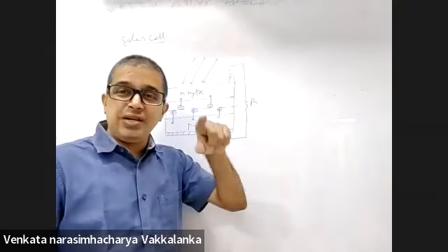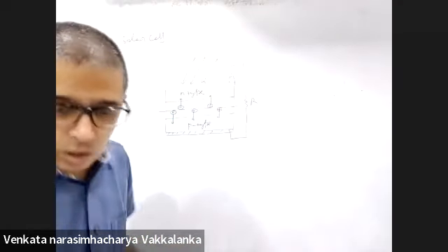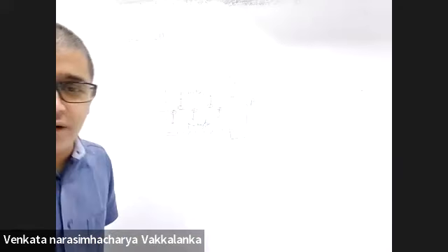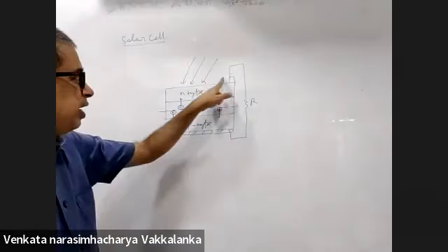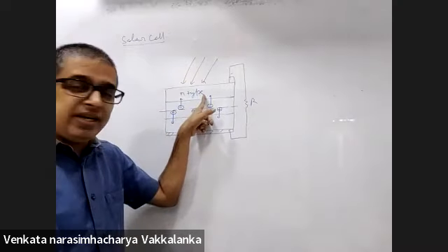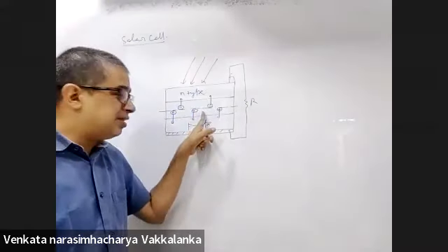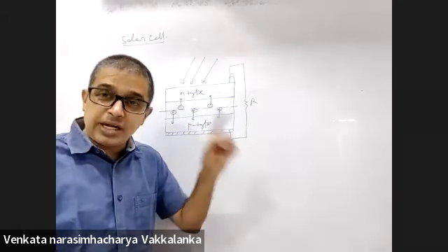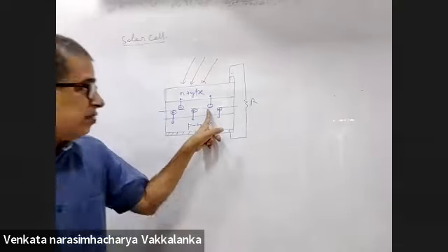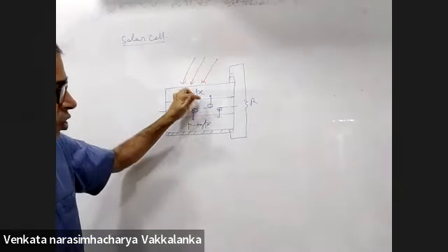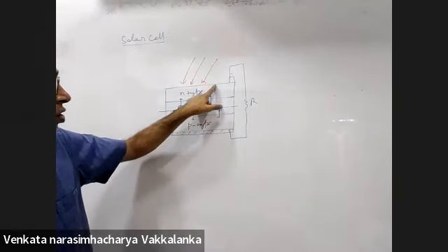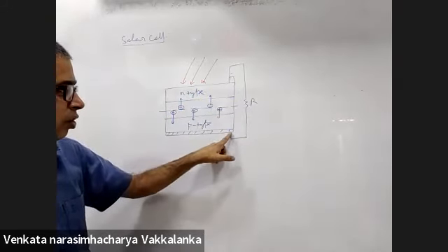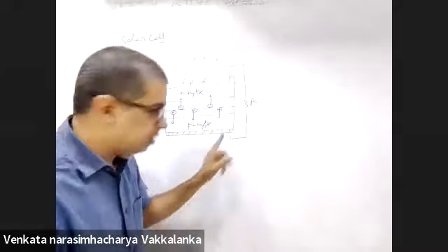Now in the construction we showed to you that light will fall on the anti-reflecting surface and then on the n-type material. Here we didn't show the anti-reflecting surface. N-type material it falls. There are electron-hole pairs generated. Right? The material should be so designed that the electrons will be moving to this part of the circuit. Positive holes will move to this part of the circuit.